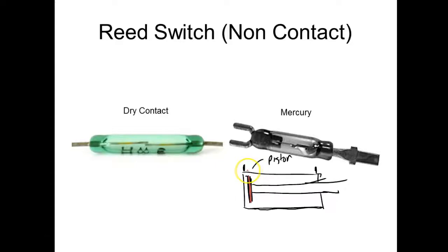And then out here, they'll mount one of those reed switches. And now what can the control system tell? Well, the control system can tell if the piston is extended and when it's what? When it's retracted. And those are actually mounted on the outside of the cylinder. And these are usually reed switches because they're what? They're so cheap.